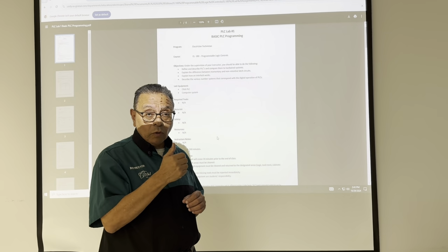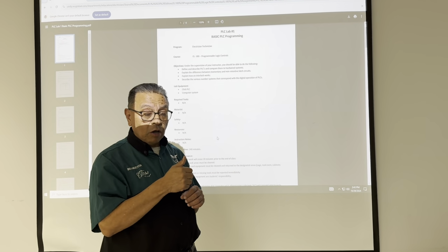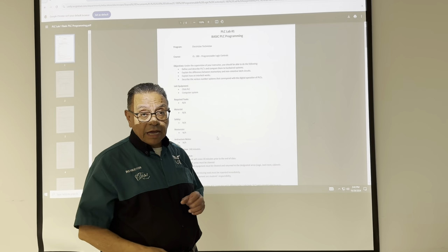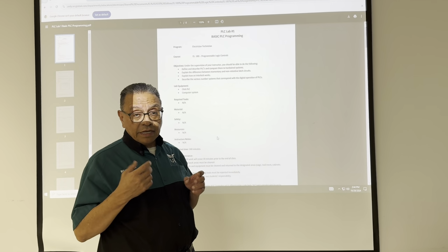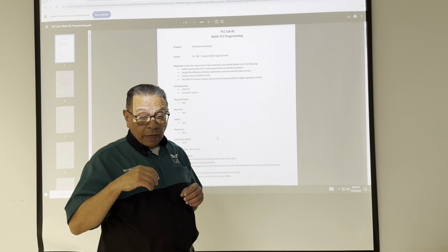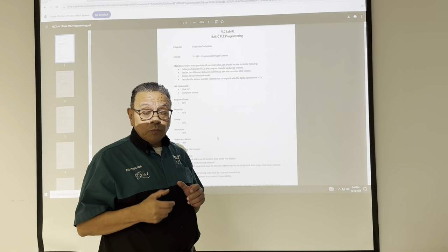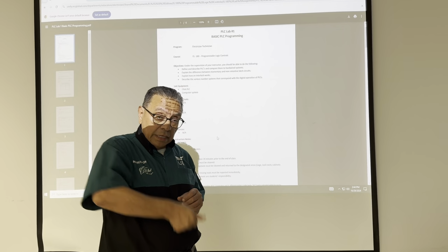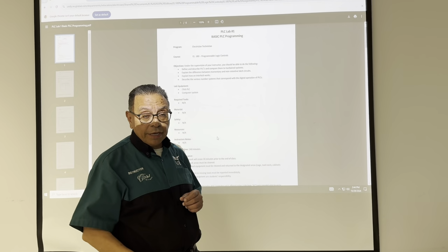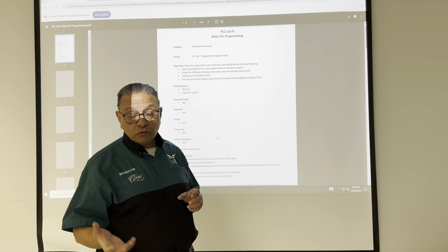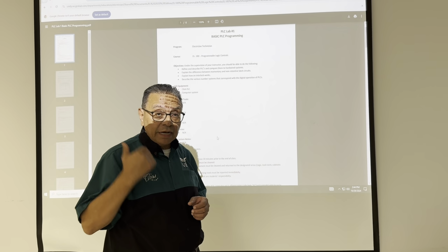The red one is used to stop, and the green one to start. Both of them internally are interconnected in a series circuit. And as a push button, the green one, immediately when you release it, it will disconnect the output. It will de-energize the contactor coil, stopping the electrical motor.